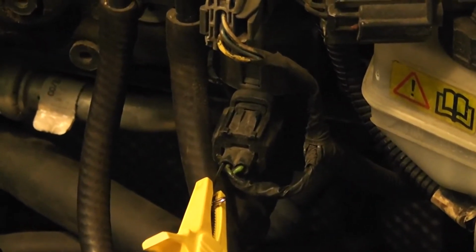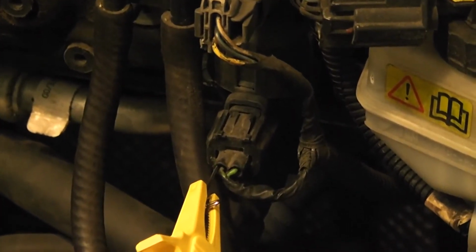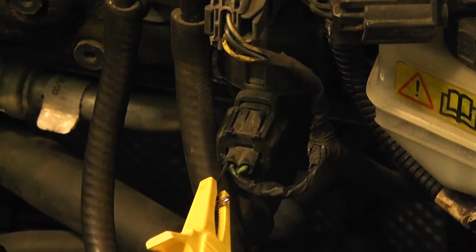This being a ground side switch circuit that reads 12 volts on one wire, 0 volts on the other, that would be what a ground side switch circuit would look like if it was being turned on. So it should look like that if it was being turned on. The problem is right now with just the key on, that circuit should not be being turned on. So we have an issue here.